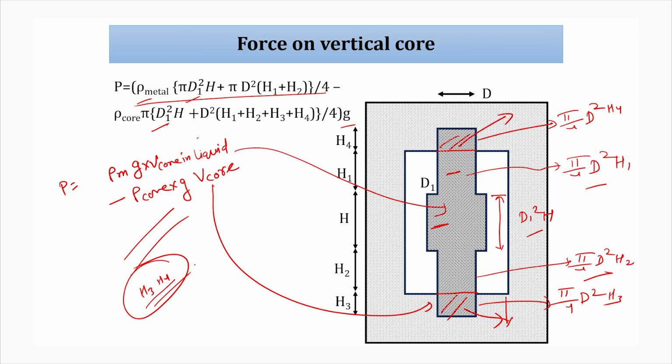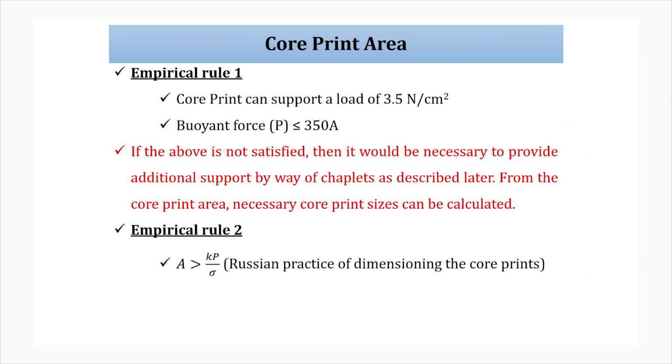If you know P, the unbalanced or upward force, it should be managed. Otherwise, if metallostatic pressure or hydrostatic pressure is acting, it will break the mold. To avoid that, we have to hold the core print by some length, by some dimension.